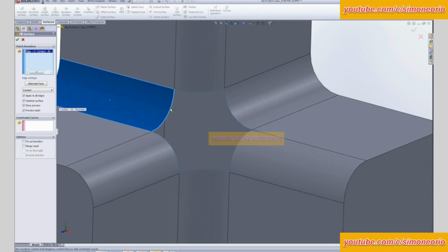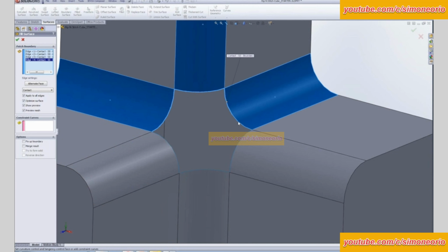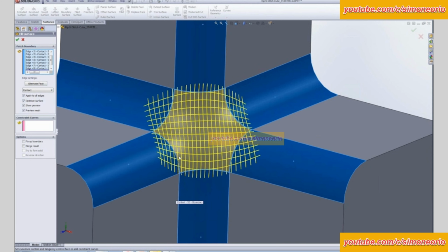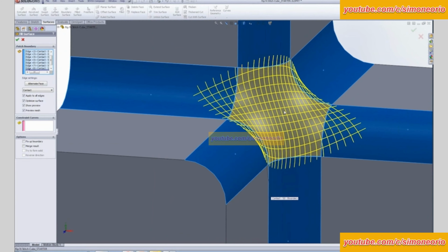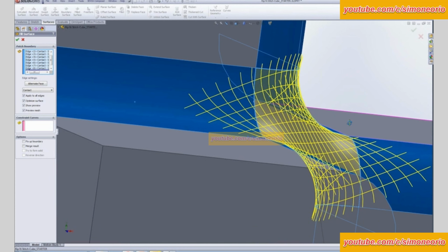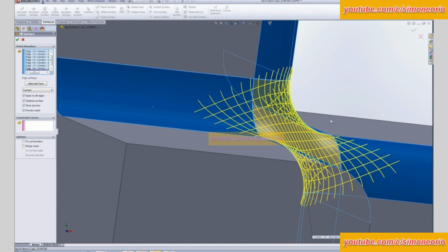So what I'm going to do is pick each one of these boundaries here. Okay? And utilize this fill surface command. You'll notice that these are open edges because our part now is hollow, now that we've ripped it. Okay, and it's just a surface body. So as I come in here and use the fill command, you can see what that fill is doing for us.